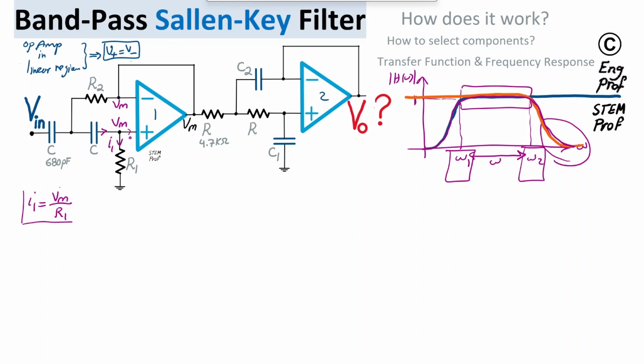So that's good. Let's refer to this as equation 1. Now let's write a KVL, or Kirchhoff voltage law, across these two components in series. Basically, adding the voltage drop across them will give me the voltage at the midpoint, or Vx. So writing a KVL, I have Vx is equal to voltage of cap plus the voltage of R1, which means the current I1 times the sum of the impedance of these two in series.